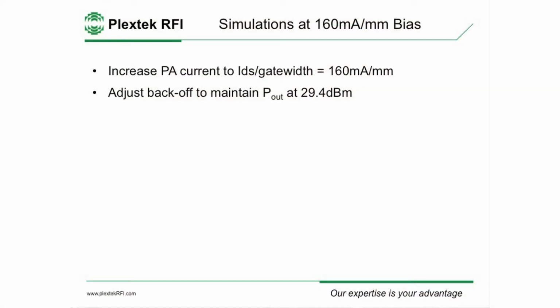And now, what we see, the first thing to notice is we've got a nice healthy margin on the spectral regrowth here. That's good, that makes us feel more comfortable. The constellation plot is cleaner. You can see gaps between all the constellation points. It's not perfect, but it's never going to be. And the eyes, you can see clear gaps between all of these sampling instances. And the EVM is 1.3%, which is actually very good. You can receive QAM 256 modulation with a lot worse EVM than that.